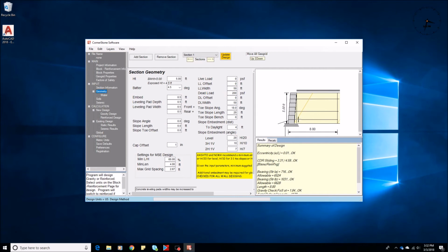Four feet is simply from the front of the block, typically a foot, another 6 inches to a foot. 4 feet gets the grid beyond the failure plane. So we have enough embedment where we're actually getting some lock into the soil.